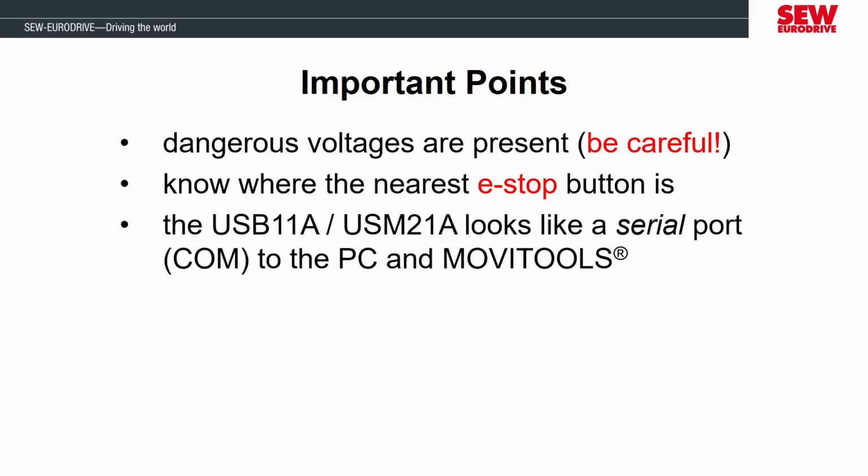When we're connected to the MOVIDRIVE over the USB to serial converter cables, the PC recognizes these as COM ports. I will show you how to select the correct COM port in the MOVITOOLS software, but it's possible that some PCs will have software access limits that don't allow the USB cable to be recognized. If you have an issue where the USB cable isn't recognized and switching to a different USB port doesn't resolve it, you will need to contact your IT department to assist you.